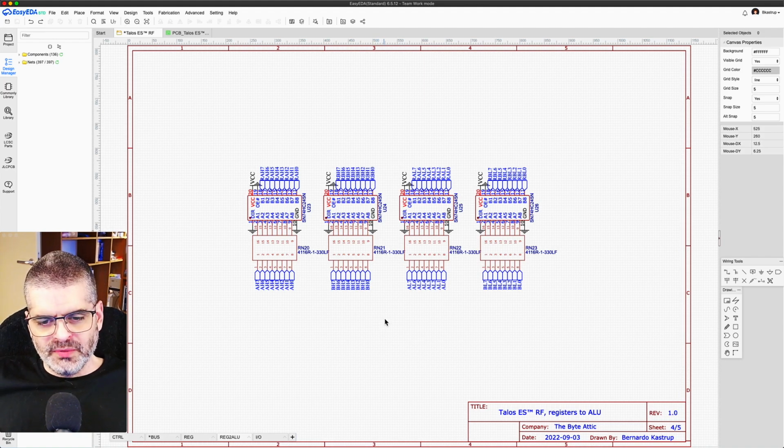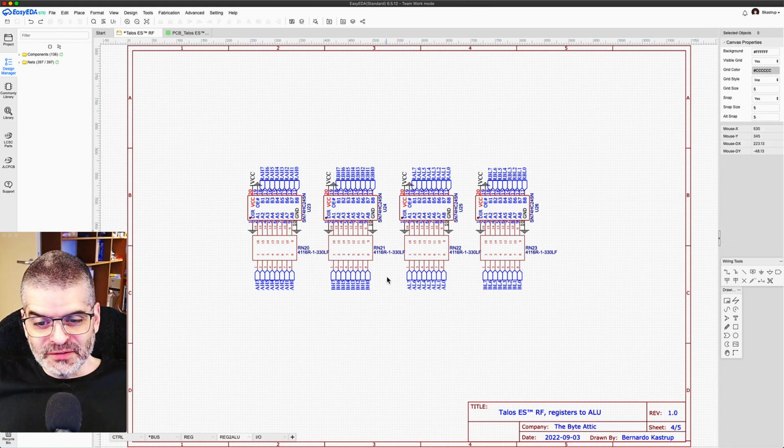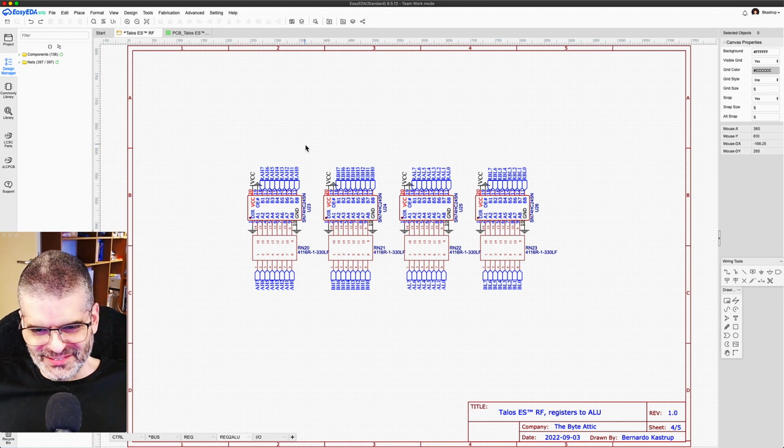One valid criticism would be to say, well, if you are actually doing an RC low-pass filter, then why 33 ohms? Because the rationale behind that value is to match the impedance of the trace. But if what I'm doing is absorbing reflections from the backplane connector, then maybe there should be another value that is better. Maybe, but 33 ohms works just fine. I didn't characterize the backplane connector to calculate its impedance. Sorry guys, this is a hobby. I am retired from technology. I'm not going to do anything that I don't find fun and I don't find cool.